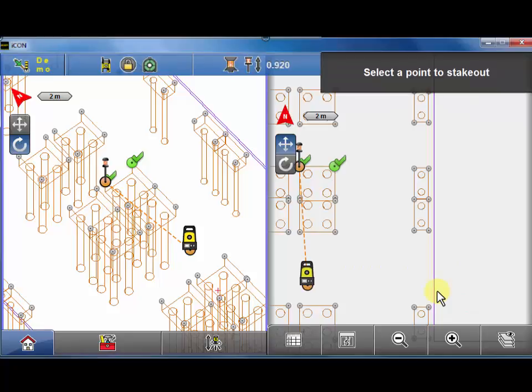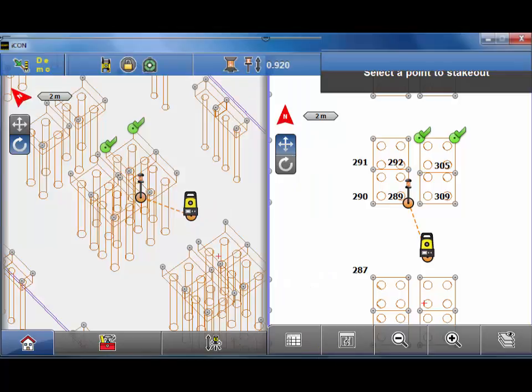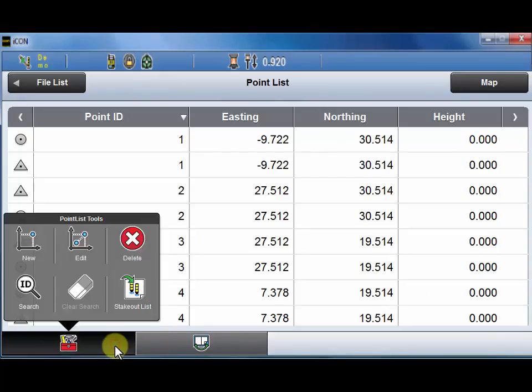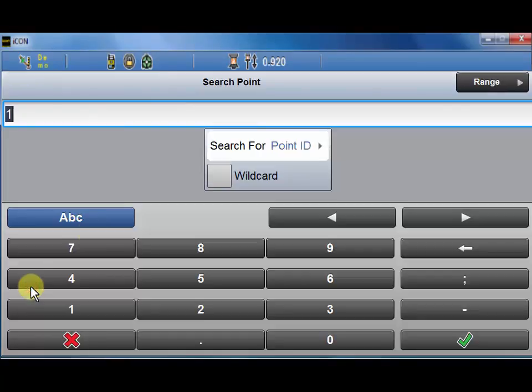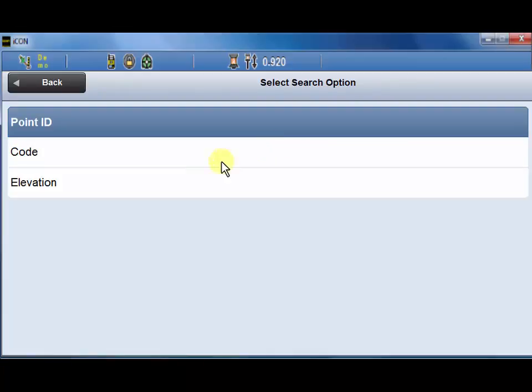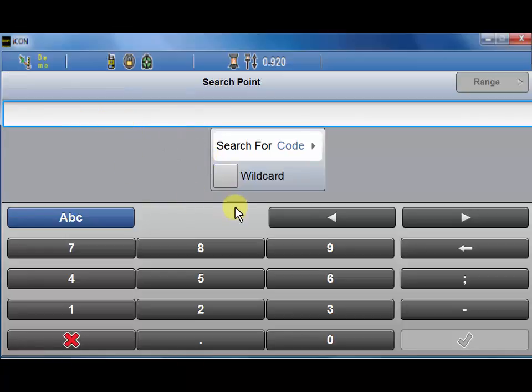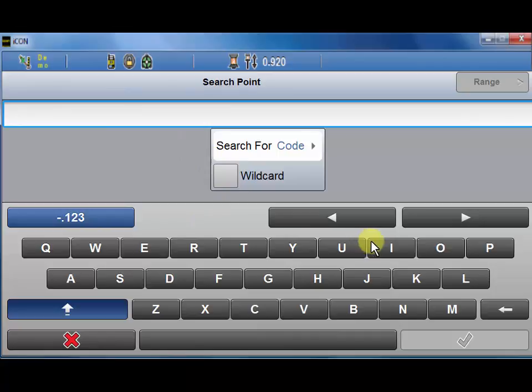For normal projects, typically several thousand points are required per deck or floor. With the new automatic point selection feature, we can define a list of points which we wish to lay out. In this way, we can follow the points in a predefined list either by order or by the physical distance to the TPS position, last point, or a known point.